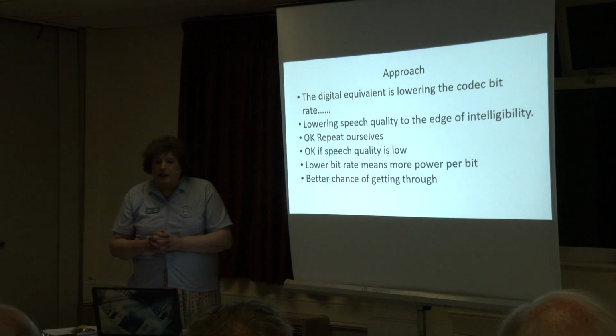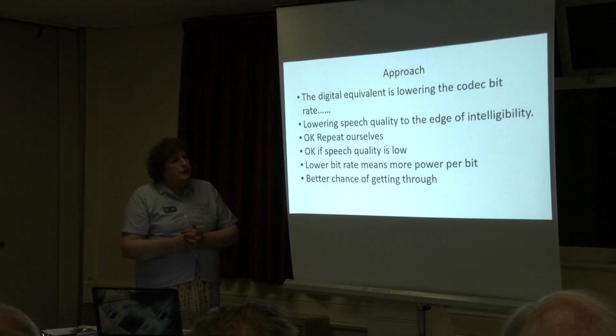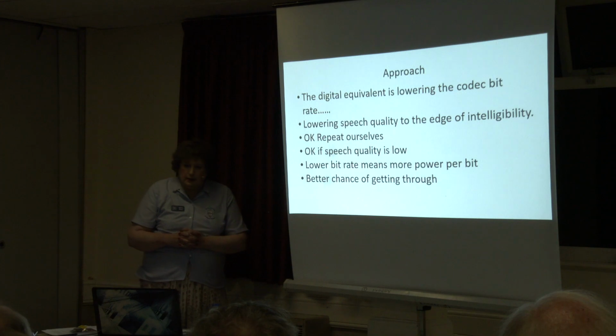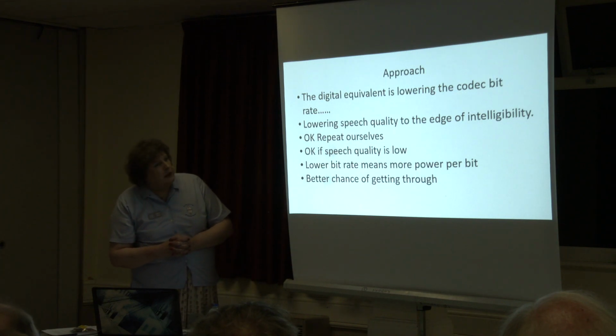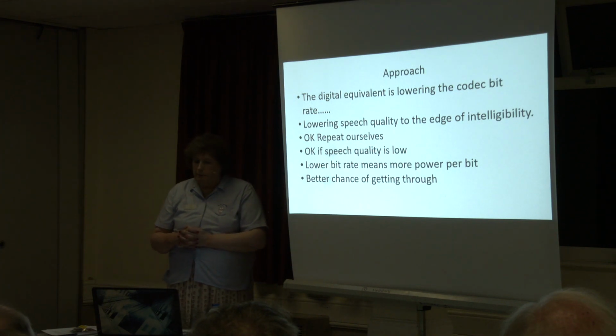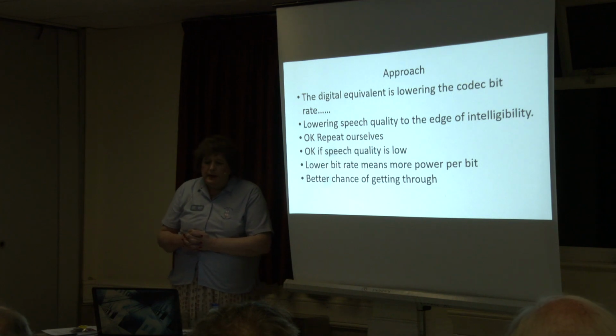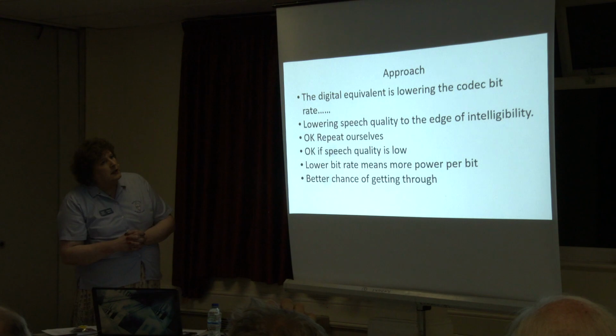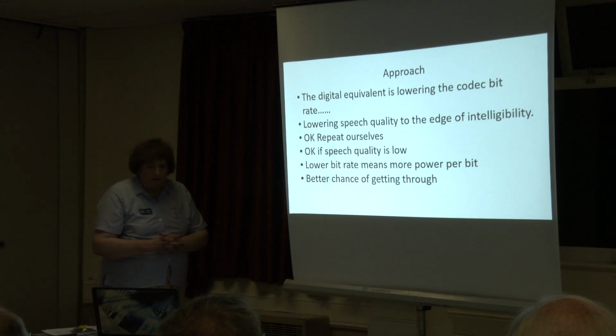We can still predict what is actually going to be said. The lower bit rate means we actually transmit more power on a particular digit, whereas if we increase the bit rate, we use less power per bit. So the lower the bit rate, the better chance of actually getting through.